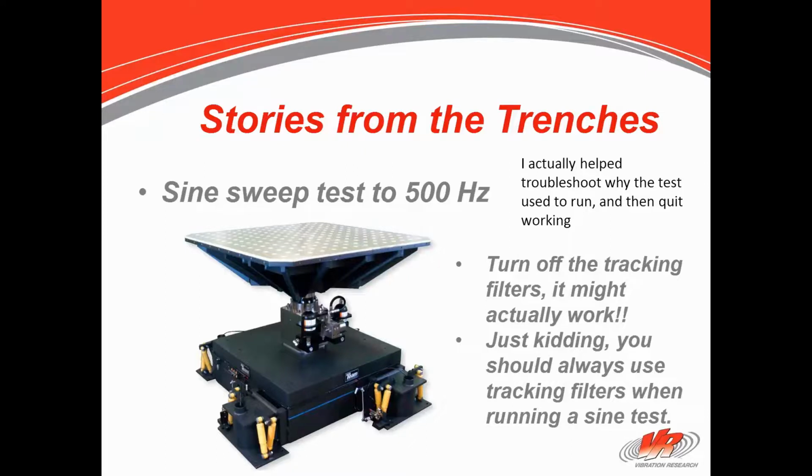Well, doesn't matter. I got my report, and that's what went in the file. So I implore you, if you really want to test your product, you should never turn the tracking filters off on a sine test. Never, ever.